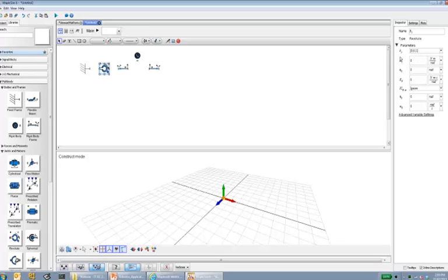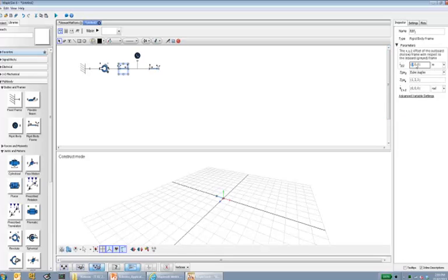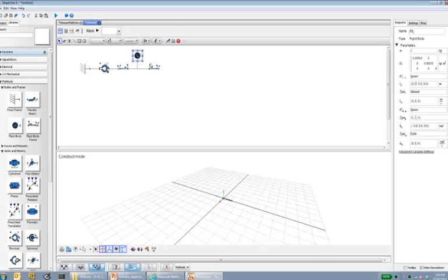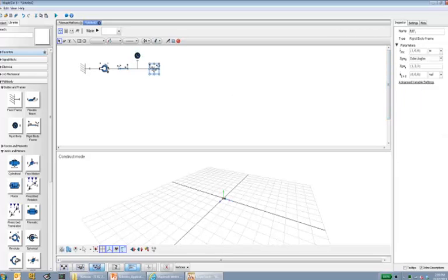The connection is made via ports in each component. As you can see, this one is a rigid body frame, and the rigid body frame is basically a coordinate transformation between 2 points, or basically a point in your rigid body. The rigid body includes the mass and inertia. So right now I am defining 2 points in this rigid body, and I am separating them by half a meter. So a quarter meter in negative x and positive x.